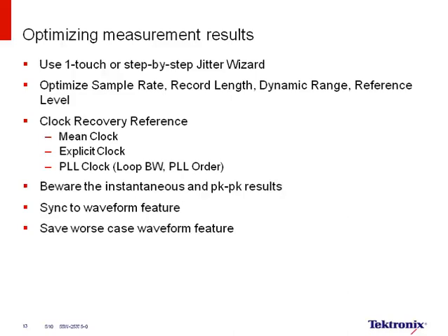When I see things like this, it's usually a clue that the jitter has some kind of a low-frequency modulation, such that as you capture more and more cycles of this periodic modulation, you get a larger TJ number. So it's key that you understand how these measurements set up and to understand why they will change depending on what the setup is.